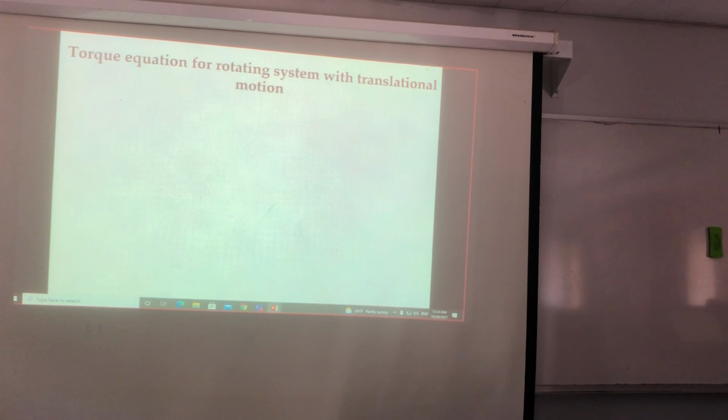So now what I have is J d of delta omega by dt equals partial TE by partial omega delta omega minus partial TL by partial omega delta omega. This can be written as partial TE by partial omega minus partial TL by partial omega, multiplied by delta omega.